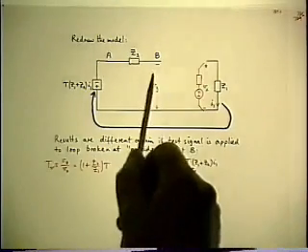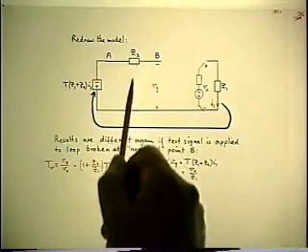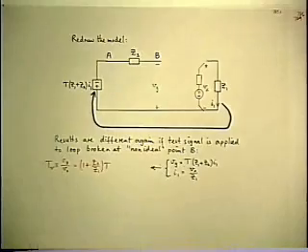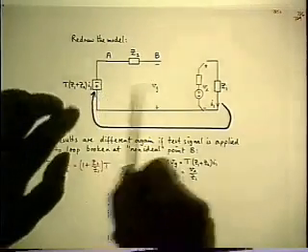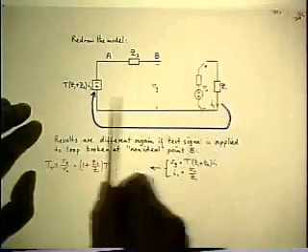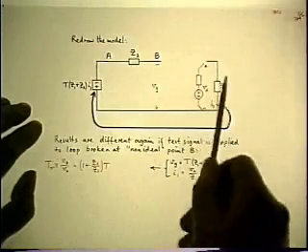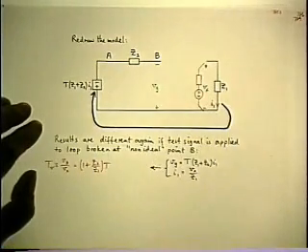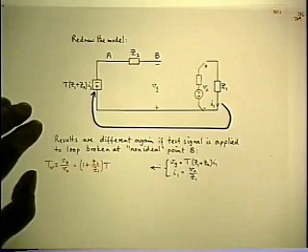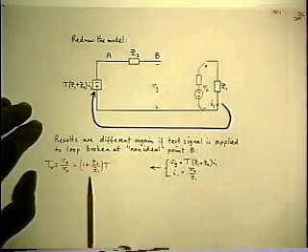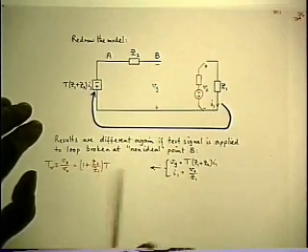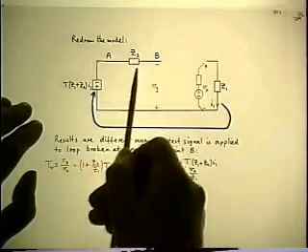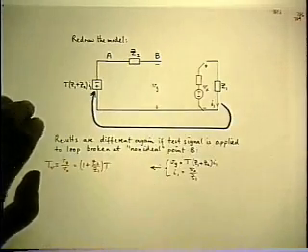So what you've done by breaking the loop is you've eliminated the effect of Z2, but it really belongs in the correct answer because it's part of this divider ratio that gets you from this generator to the signal at this point in the normal closed loop condition. So the interpretation is Z2 does belong in the answer. It's inside T properly, and it's not being properly accounted for if you break the loop at that point.